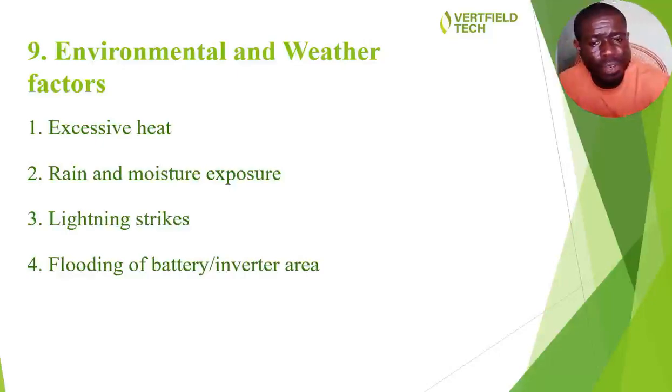That is one of the basic reasons why you are not advised to put your solar panels directly on the roof, on an iron roof or zinc roof. Always make sure you make provision for rails, the solar accessories, so that the panels can sit on those accessories and there can be good ventilation under your panels to cool them off.